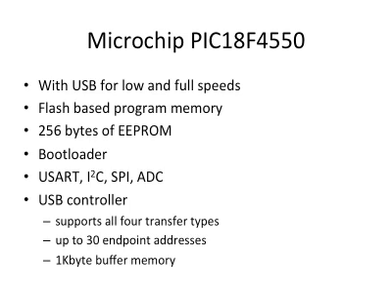So essentially, inside the chip, normally you have your application firmware like you design in your lab 2 and 3. You can just program the chip using the PIC tool. Okay? Without the PIC tool, how do you update the programs, the firmware in the microcontroller?